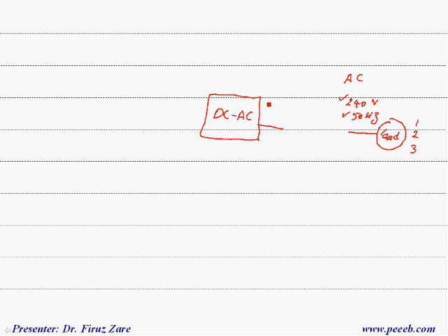But the point is that because the output voltage is based on a pulse pattern, in real time we have a PWM output voltage. This type of voltage is not suitable for different applications. So that's why in this case we need to have a filter, and the output voltage can be a sine wave with a little bit of harmonics, and the harmonic level depends on the type of filter.